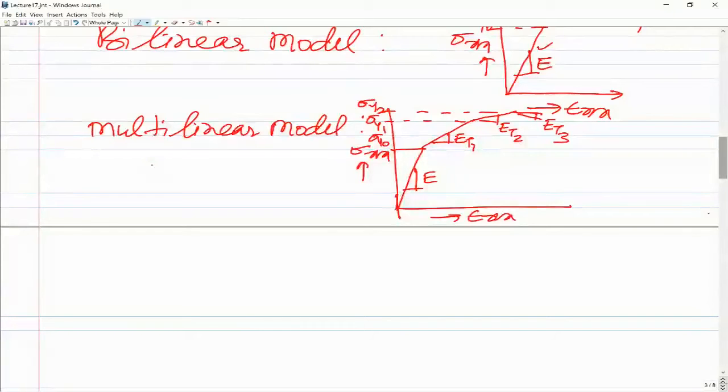It will be direction dependent, right? We cannot specify uniaxial yield. Yeah, that's what I'm saying, that when you use the CE matrix, one difference is going to be there in CE, and another difference is going to be in the yield function. The yield function also would be different for the anisotropic material, and the CE matrix will also be different.